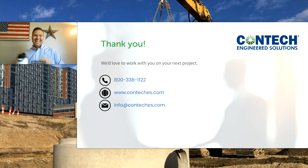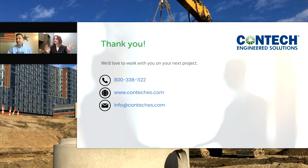That's right. If you have a question, type it in the question box and I will try to get to it. Our first question is, what are the standard manhole sizes for Contech HDS systems? I can get this one. Standard manhole sizes are between 4 and 10 feet, but in certain areas where there is precast availability, we can use anything from a 3 to a 12-foot unit.